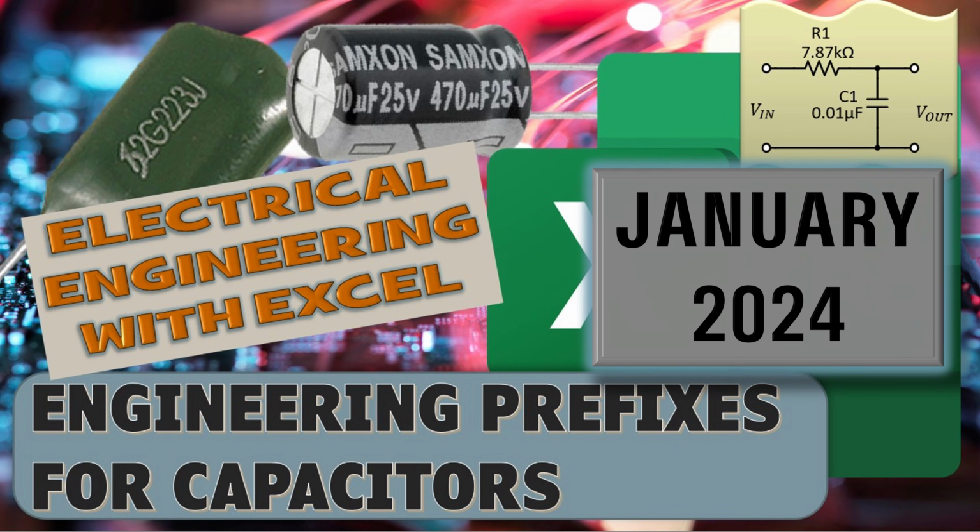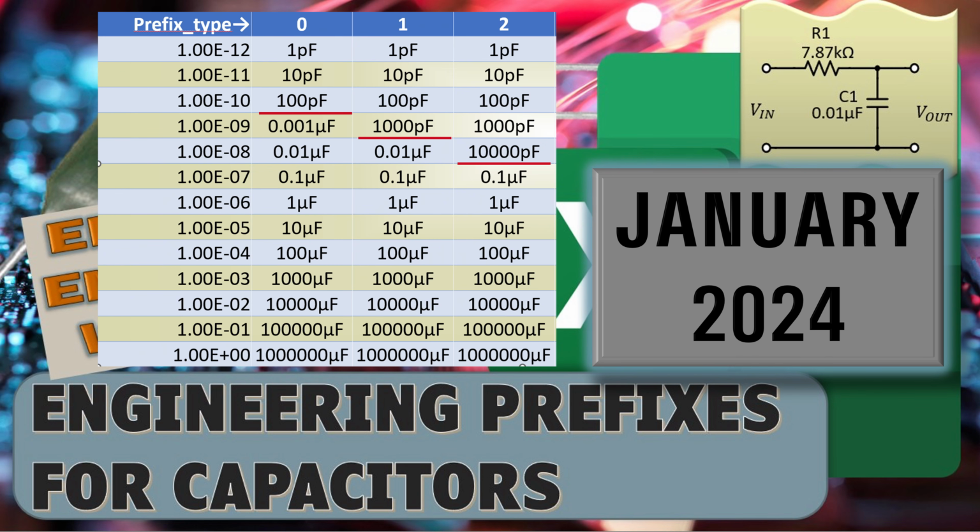In January 2024, I developed a similar user-defined function tailored to capacitor values. Capacitor manufacturers and most schematics shy away from capacitors in nanofarads and millifarads. They usually split between microfarad and picofarad at various levels. The function has arguments to program the output where capacitors are either in picofarads or microfarads and not nanofarads.